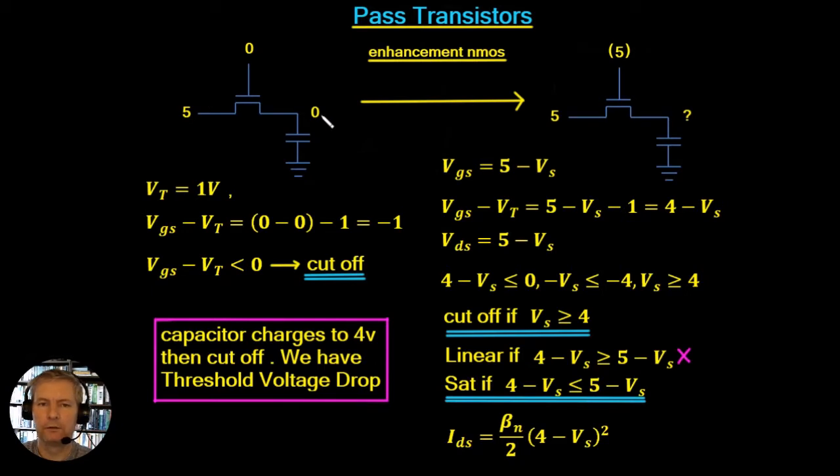So the first thing we have to do is determine what is the source and what is the drain. It's an enhancement NMOS, an NMOS device. Electrons are the majority charge carriers. Electrons travel from a low voltage to a high voltage, and the low voltage side is the source. So this is the low voltage side here, so this must be the source of this transistor.